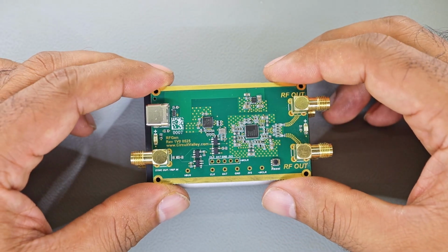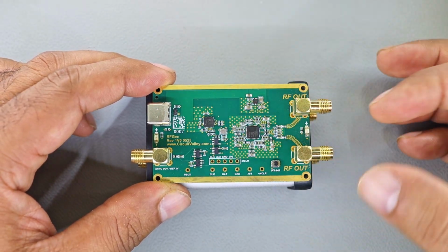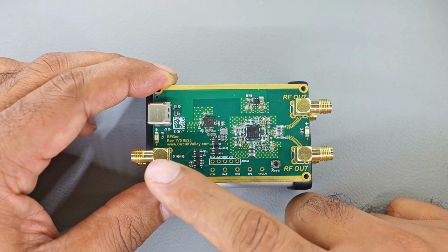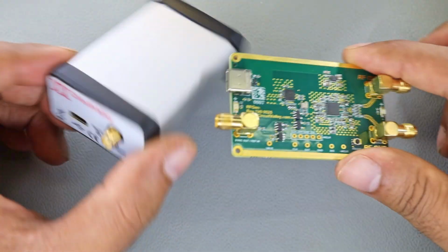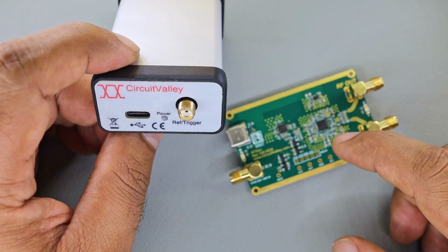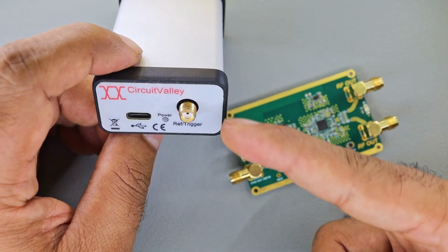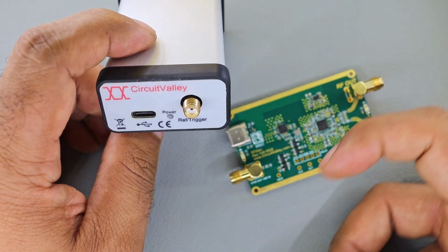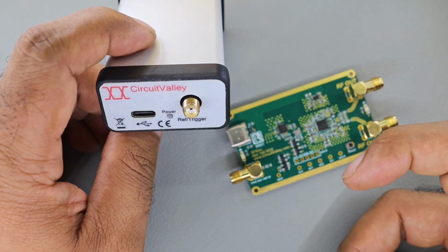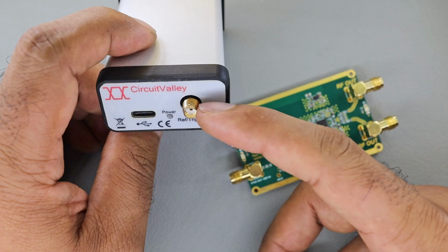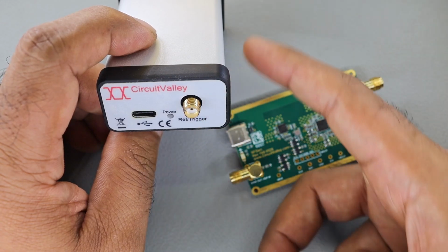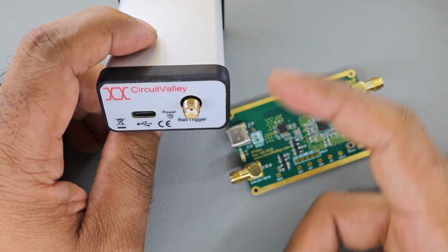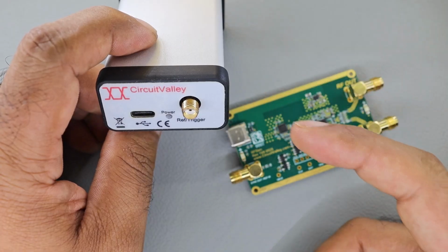It's based on this little hardware. It has a USB and few other components to provide you two RF outputs. As a feature, it provides you third input and output as well, and this is the aux pin, and these aux pins allow you to provide external reference for the PLL. It can also provide you sync output when system goes into sweep mode and generate sweeps of the frequency to test filter or provide a tracking source for a spectrum analyzer. Then this input and output can be configured in various ways: synchronization output, reference input, and synchronization input as well. So it can also synchronize to external devices, sweep frequencies or change frequencies on request on I/O.